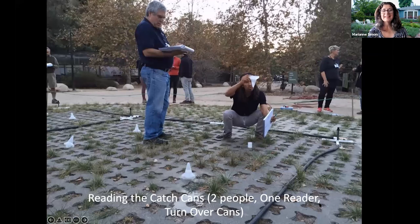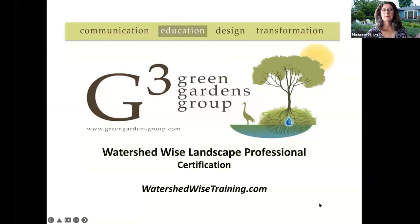And then once the test is done, you start the process of diligently, carefully reading the data. Ideally, you do it with a partner where one person is reading and the other person is recording the data. At the end of it, as you read each can, we strongly recommend you empty out the water and turn over the can so that you are tracking your progress through the data. And that brings us to the end of our module on irrigation auditing.